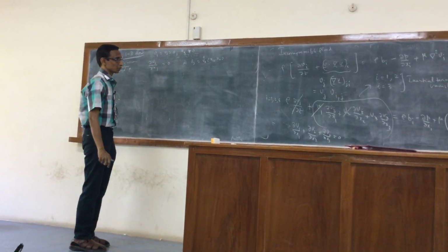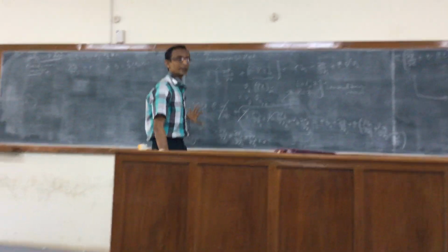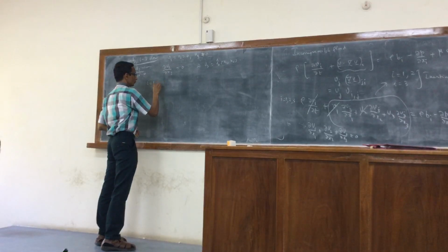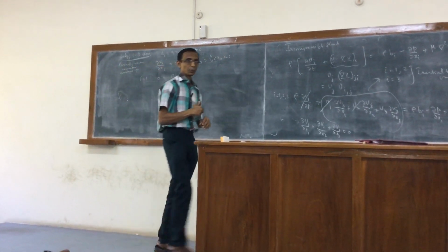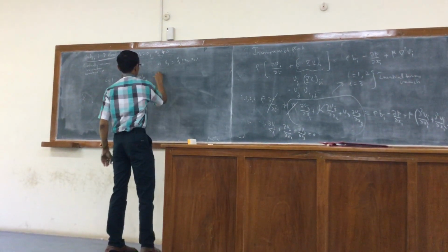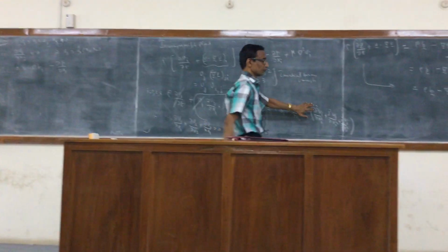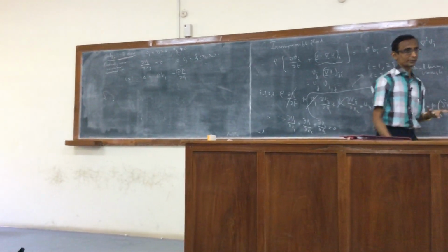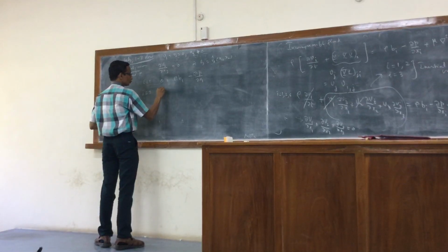The equation of motion will mean that for i equal to 1 and 2, the entire left hand side would be 0. So for i equal to 1, I get 0 equal to rho b1, the component of the body force in the o1 direction, minus dp by dx1. That's all. Because V1 and V2 are 0, I won't get the viscous terms also. It's the simplest possible case you can consider. So i equal to 2.